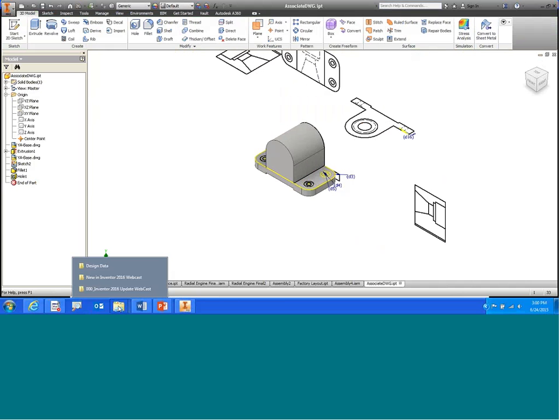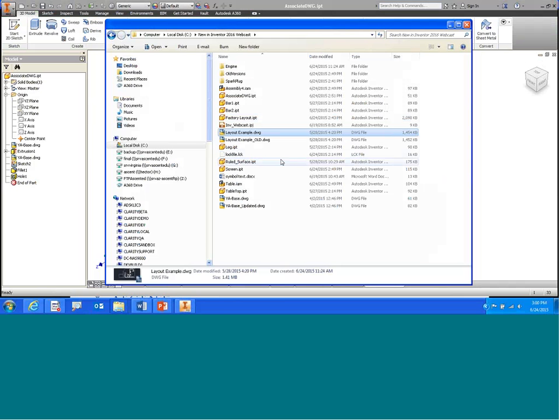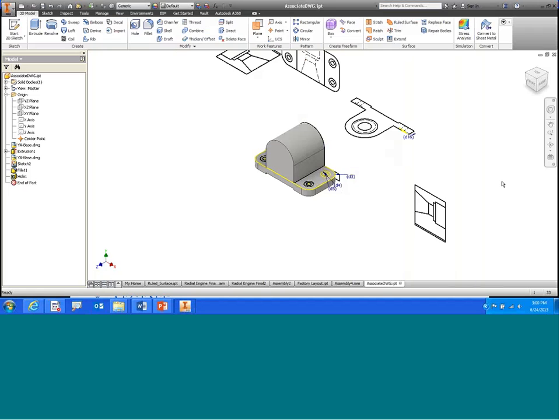Now again, I want to simulate that design change. So I'm going to flip back over into just my Windows Explorer here. And you can see that the YA base, this is the drawing that I referenced. I referenced it twice inside my model. And I can go in and just rename that, say, old. Take the updated model and rename that to simulate my design change. Sounds great. I can flip over here, and immediately you see the lightning bolts have appeared on both of